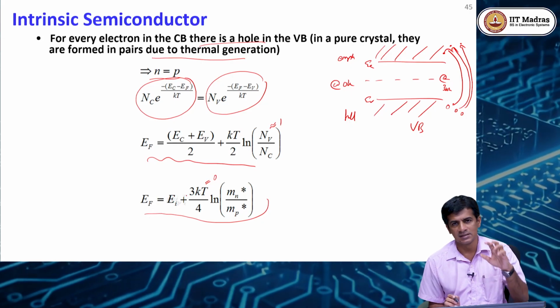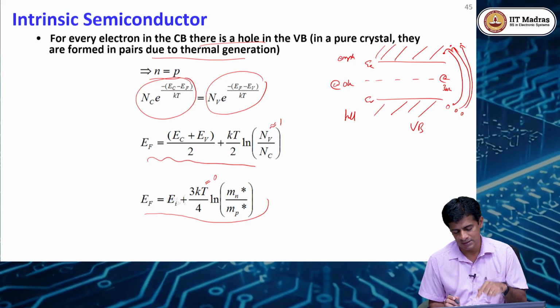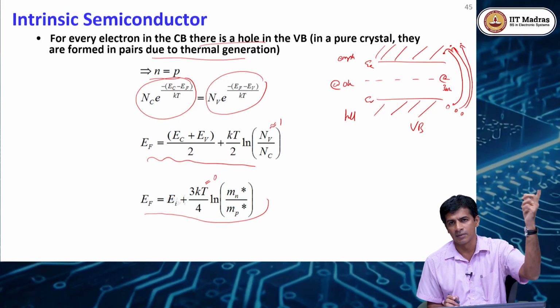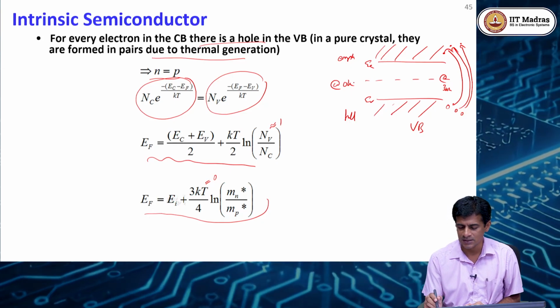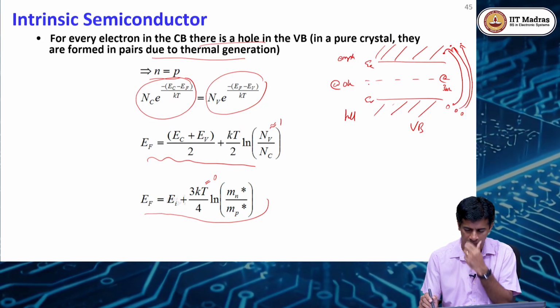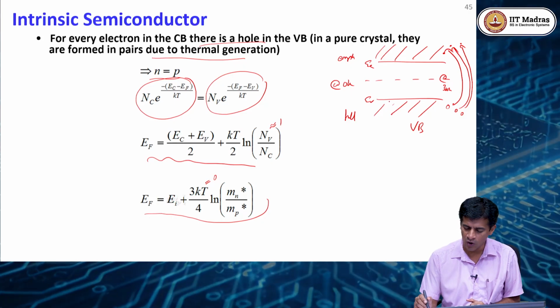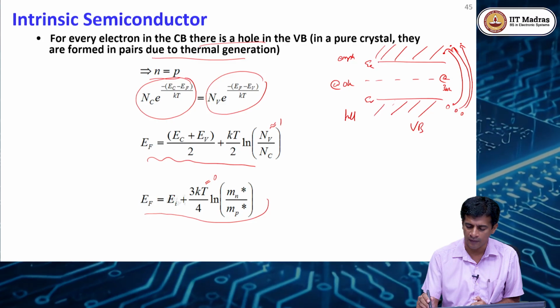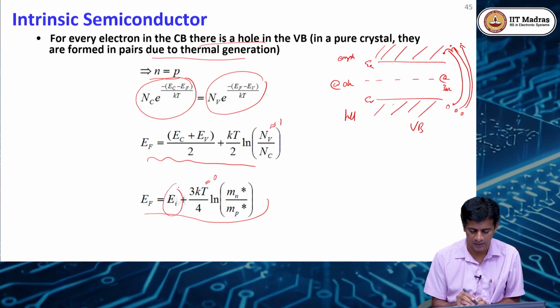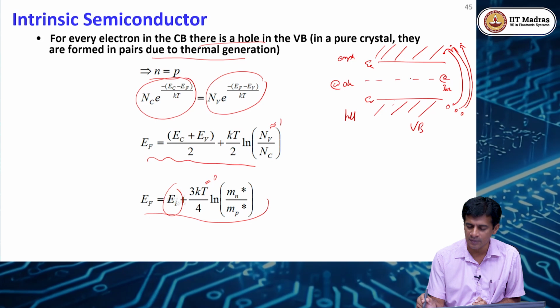All right. So you can see this is in sync with the earlier Fermi level definition. We saw that in the case of systems with discrete energy bands at 0 Kelvin, the Fermi level lies between the top of the occupied level and the bottom of the unoccupied level. This is exactly half. So the Fermi level lies at the middle of the band gap.